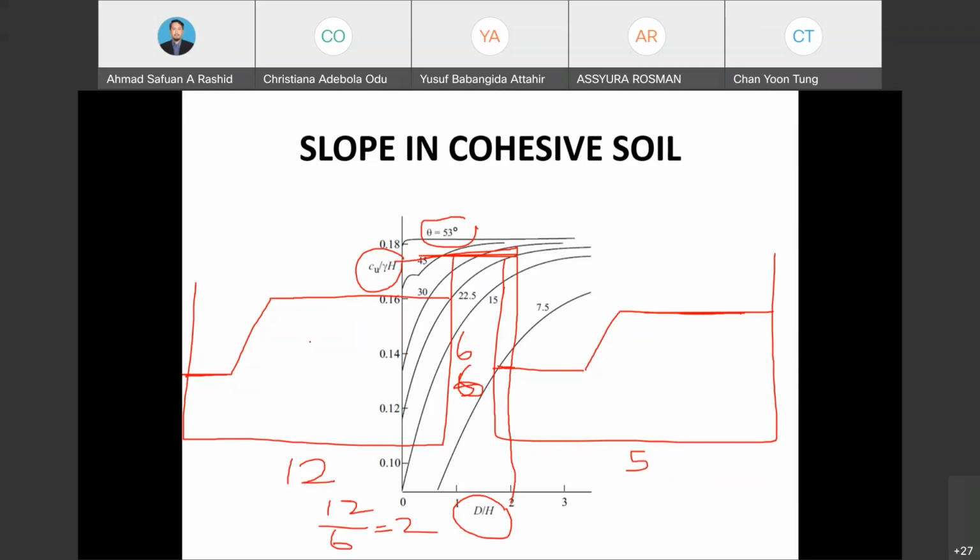For example, for my case on the deep mixing method, this preliminary chart can be used by the contractor or by the designer when they want to have a very quick judgment on what will be the strength, what will be the bearing capacity for his particular site. Then to have a very accurate result, he or the designer can run the full numerical modeling test.